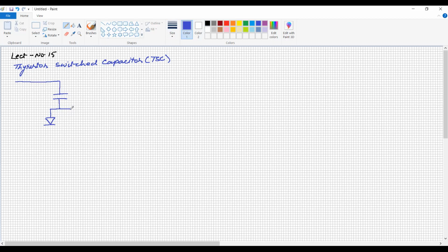it is already discussed. One Thyristor can handle 4 kV to 9 kV voltage and current from 3 kA to 6 kA. So as per the requirement, or say the voltage rating of the line, they may be connected in series.